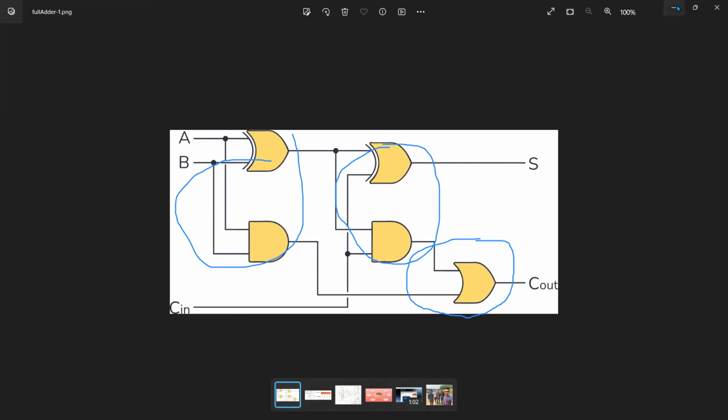So we are going to mention the OR gate now. How are we going to write the OR gate? Assign C out is equal to C1, this is the OR sign I'm going to write, or C2. This is the OR gate. This sign represents the OR gate. Now I'm going to end this module. End module.